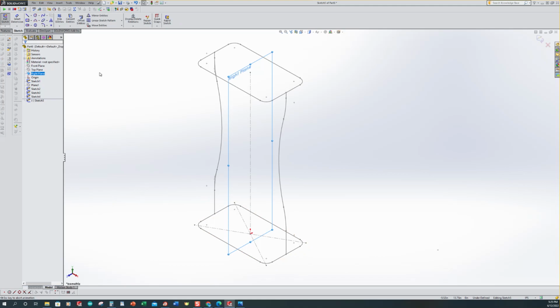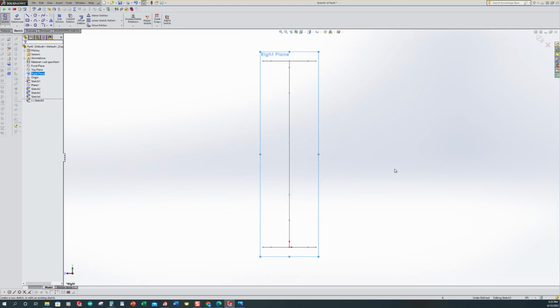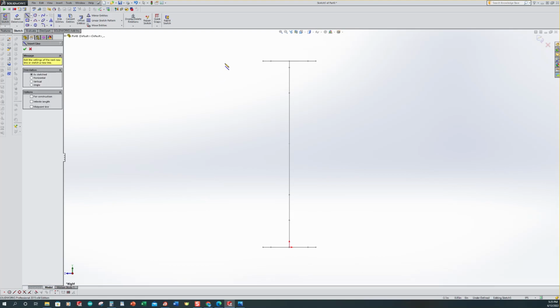Control 8 shortcut if yours doesn't orient normal. Alright, so I'm going to select a line command. Same general area, one mouse click, pull it down, release it. One mouse click, hold it down, release it. 3-point arc, endpoint, endpoint, this general area,